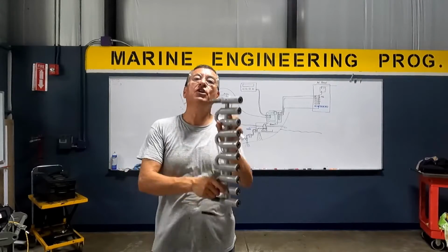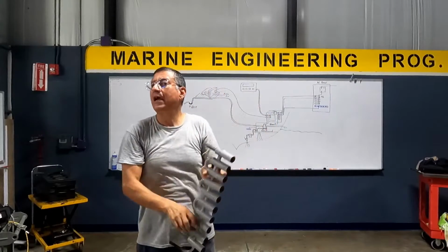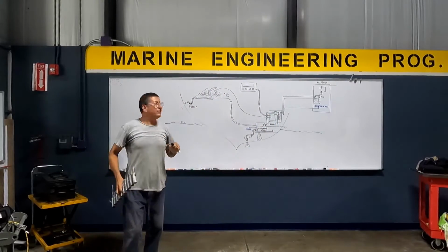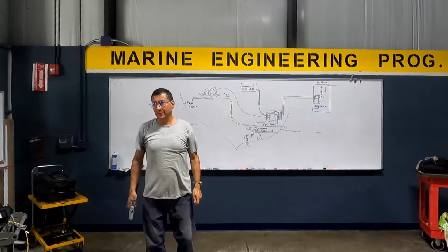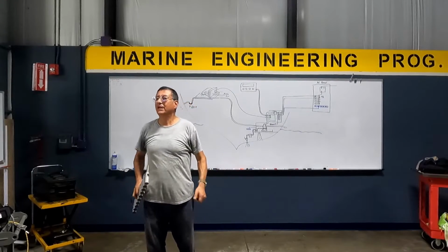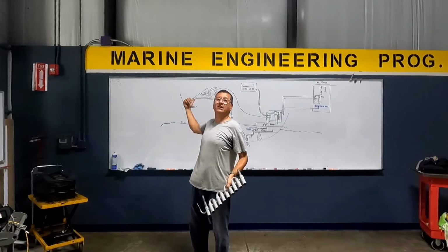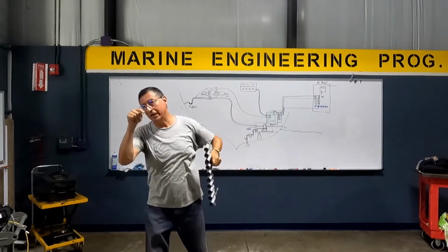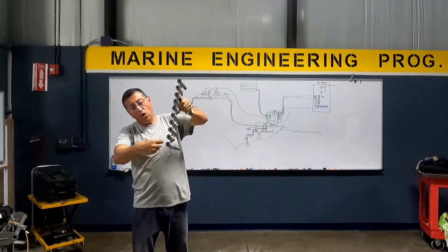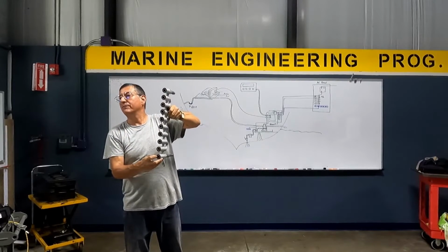Once per year. You need to do service in the outdoor coil or condenser coil, and you need to service the indoor coil or evaporator coil. Right? Both coils. In this coil is where the air filter is located. In that coil, this is the condenser coil, is located outside. You need to pass water with bleach to clean in between both of them.